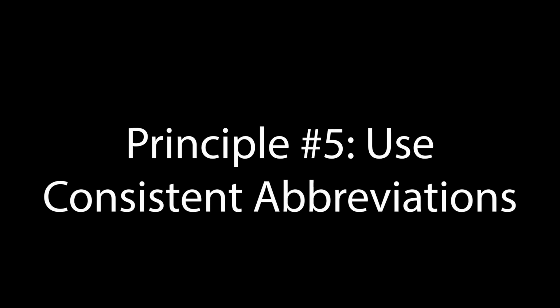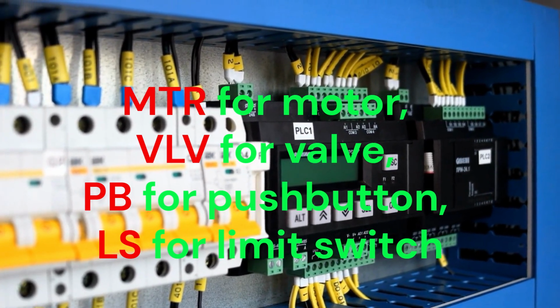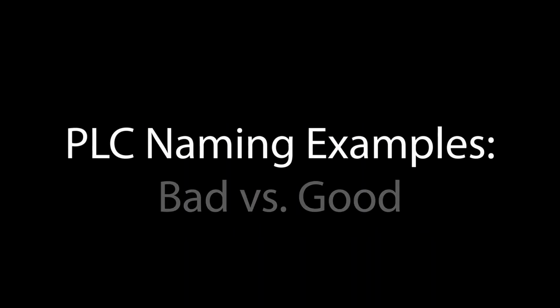5. Use consistent abbreviations. If you need to use abbreviations, create a list and use them consistently. For example, MTR for motor, VLV for valve, PB for push button, LS for limit switch. Make sure these are documented in a central location for new team members. Let's look at some examples to see these principles in action.